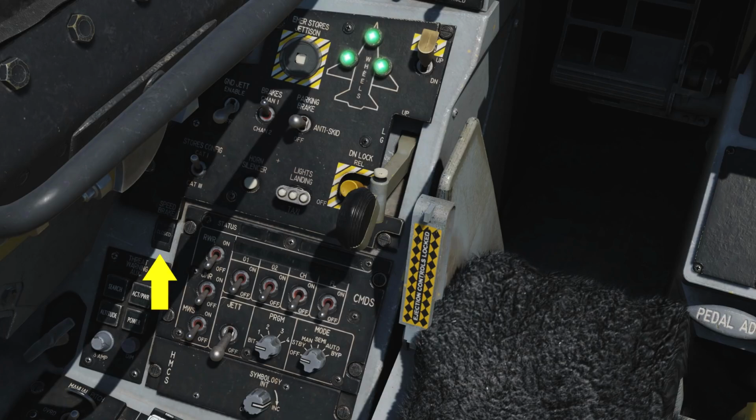The speed brake indicator has three possible indications: closed, open, and no power. When closed, the indicator displays closed. When it's open, it has a series of 9 dots, and when it has no power, it has striped lines. The stores configuration switch has positions for Cat 1 and Cat 3. This generally translates to Cat 1 being for air-to-air loadouts, and Cat 3 for heavier air-to-ground loadouts or lots of gas under the wings.